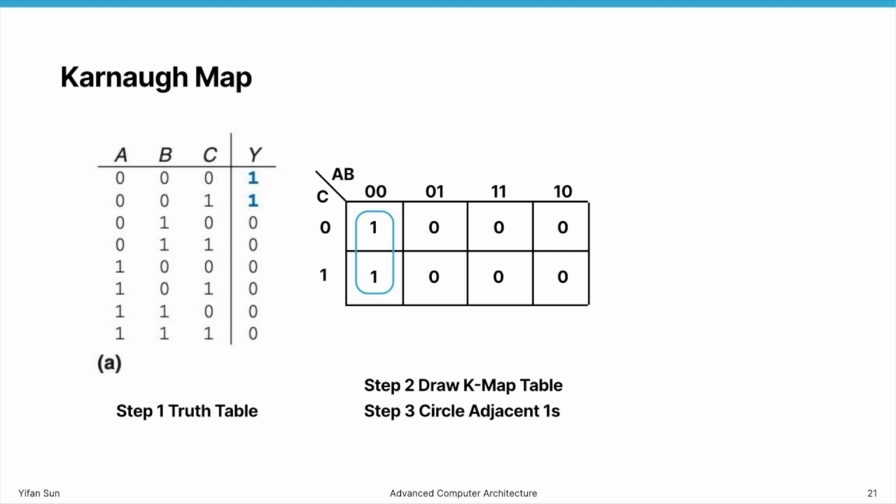So what do we do next? Remember, this form is exactly what I wrote on the whiteboard. It represents just another way to write the product with sum format. In the Karnaugh map, we know that when cells are adjacent, there will be chances to take something out. For example, these 2 cells have C prime and C adjacent to each other. So when they're adjacent, we circle them together. That's a single product. That's not 2 products. Okay.